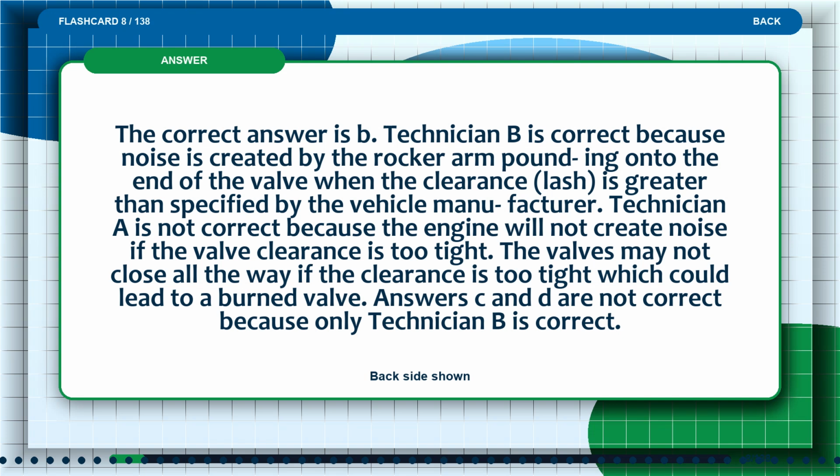The correct answer is B. Technician B is correct because noise is created by the rocker arm pounding onto the end of the valve when the clearance lash is greater than specified by the vehicle manufacturer.